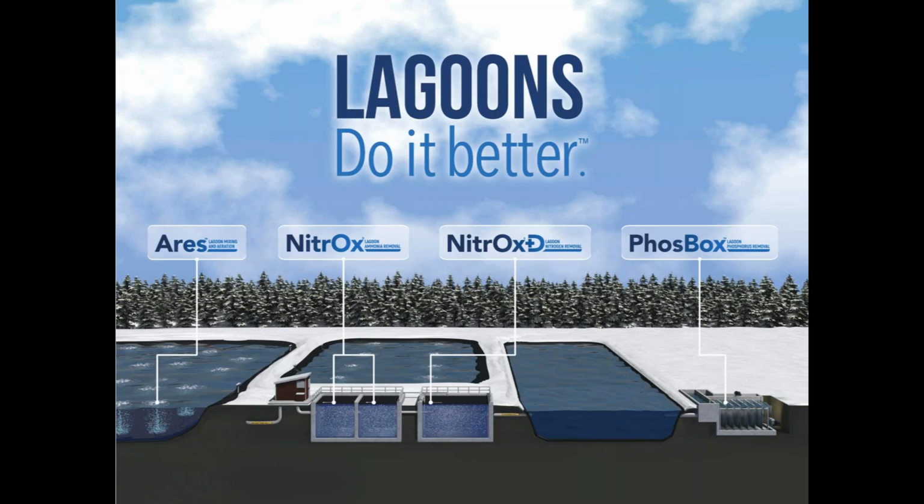This is a 2-cell reactor that's placed after the first couple of lagoon cells to remove ammonia. We basically let the lagoon do what the lagoon is good at, which is removing BOD. And then we build this reactor for the nitrifying bacteria that have very specific needs in order to get them to function efficiently in a very small footprint.